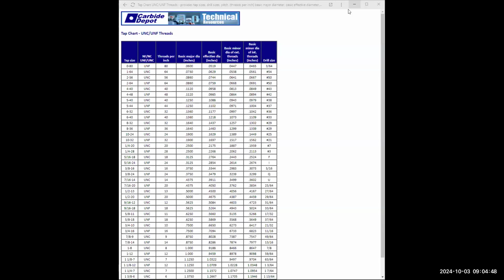Now I'm going to type in snap angle 0. And this time I'm going to type in snap angle. Got to spell it right. -41 degrees. Enter. Line. And I'm going to click right here, and I'm going to drag it down like this. Click. Enter. Type in snap angle, and then put in the value of 0. Enter. Now we have to simply clean this up.